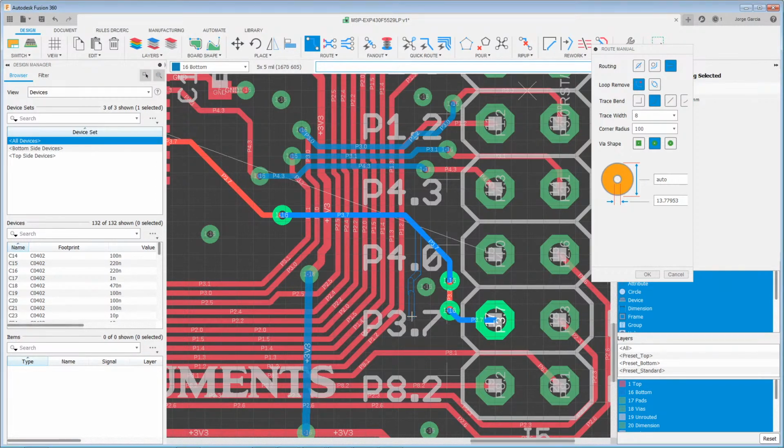Okay, you see that I started. And what's going to happen is, as soon as it sees that there is a loop there that can be removed, it takes it away. So everyone can see that. Okay, and this makes it very easy to rework traces. If you find that a trace is not optimal the way it's currently set up, all you have to do is just redo it. You just click on it and you redo it.